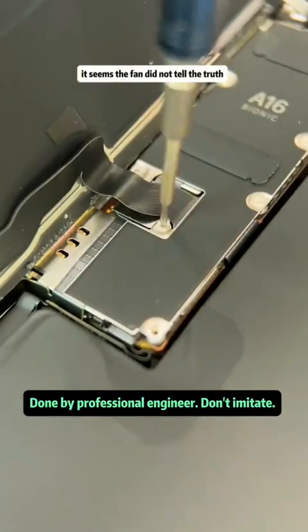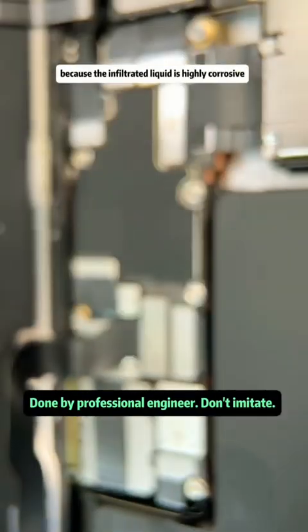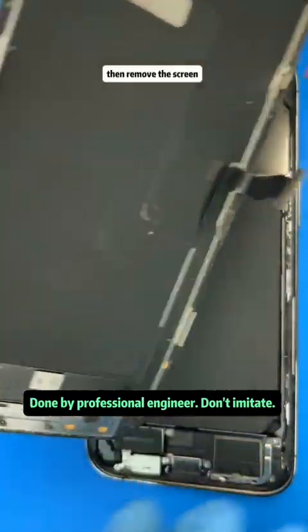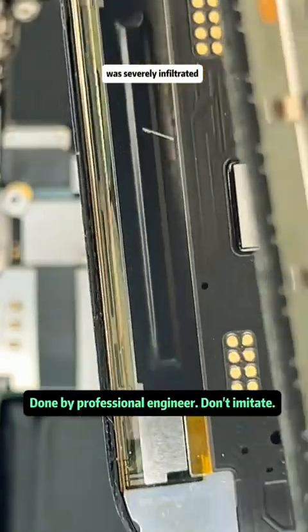It seems the fan did not tell the truth, so this also confirms why the screen bracket adhesive would separate. Because the infiltrated liquid is highly corrosive, we sequentially disconnected the battery connector, display, touch, and sensor flex cables, then removed the screen. Let's take a look at the severely separated bracket. The upper part hasn't separated, indicating that the lower part was severely infiltrated.